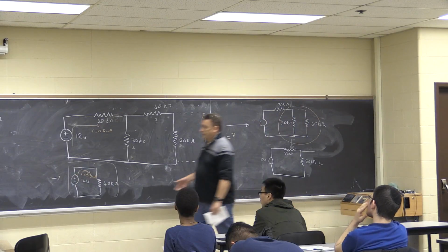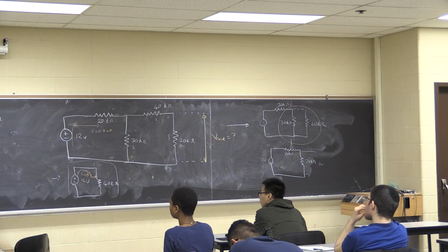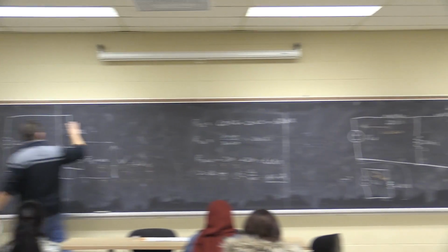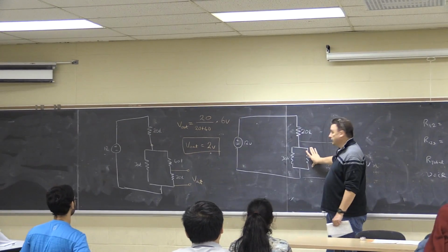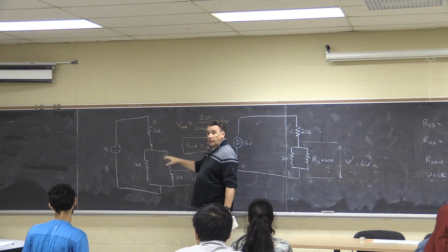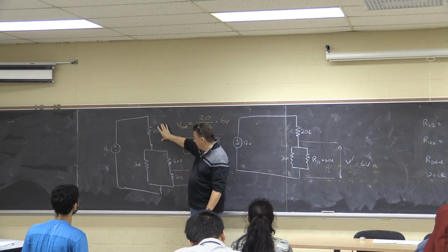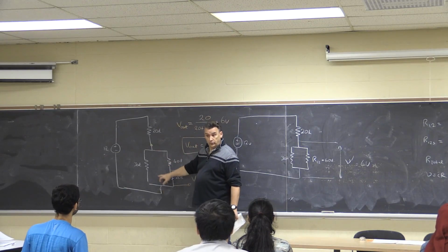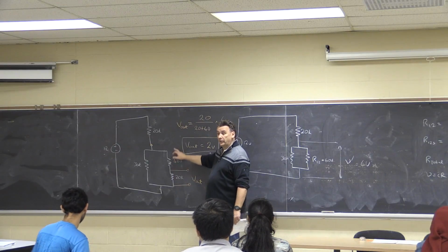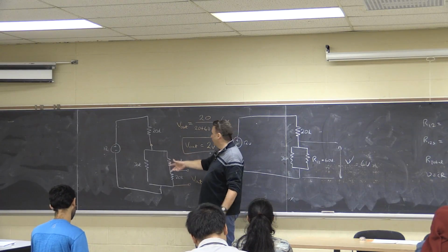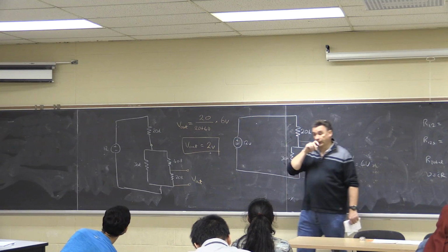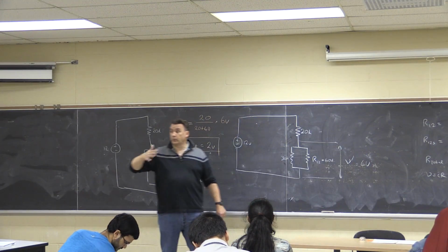That translates into this circuit, where this one's 6 volts, this is 6 volts. I recombine the circuit and make it bigger, this is still 6 volts, and this voltage here is still 6 volts. So now I've got two resistors in series, which have a 6 volt potential drop across them. I apply the voltage division rule, because they're different, and I get 2 volts. That's the final voltage. So it's a quicker way of solving that.